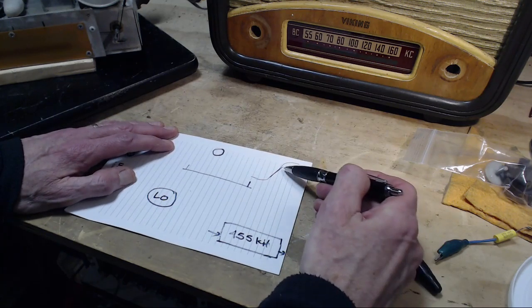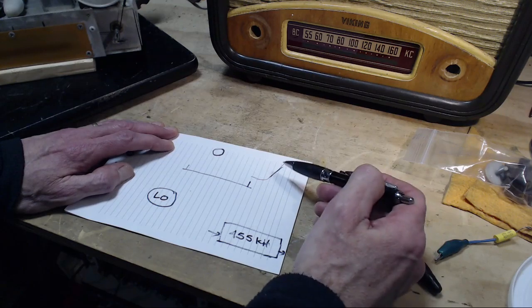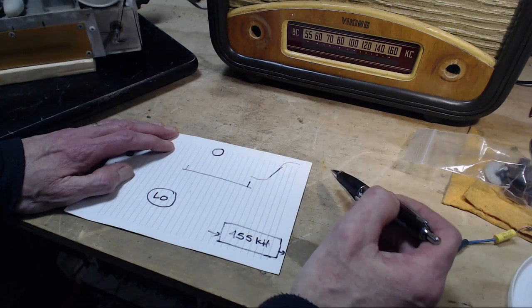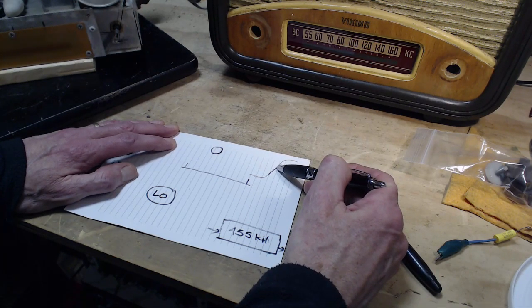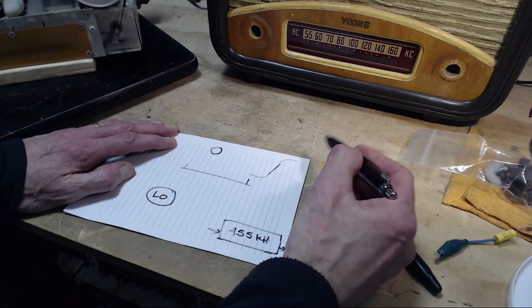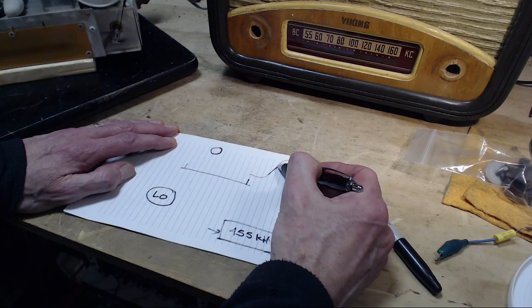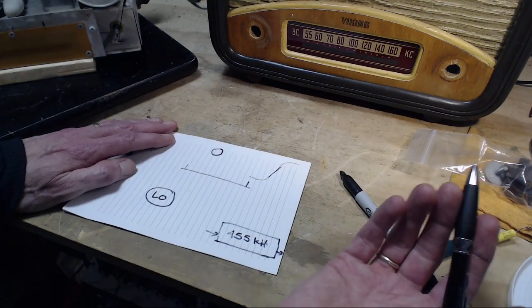If you operate the tube in this area, which is normal, this is normally where everything's being operated, in this linear area, the signal you put in gets amplified, or whatever it is the tube is doing to it, and comes out just fine. If you operate up in this area, in this curved area, something funny happens. When you feed in your signal, this area will start generating harmonics. The actual wave shape will change. The sound you hear will change.